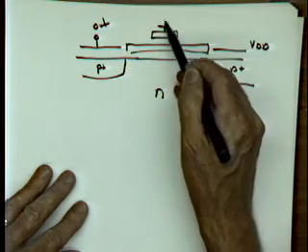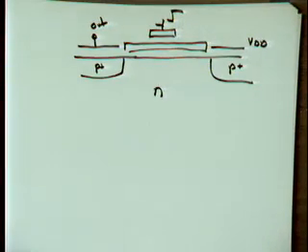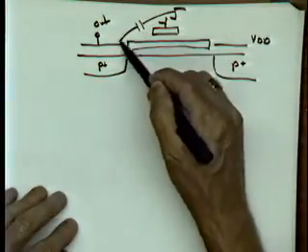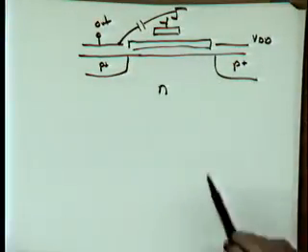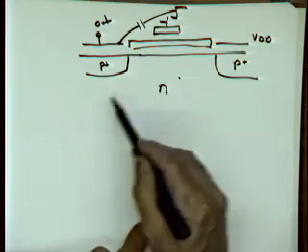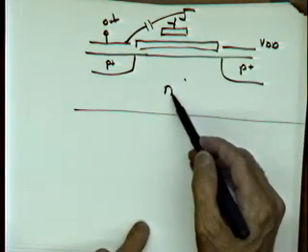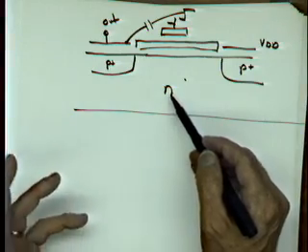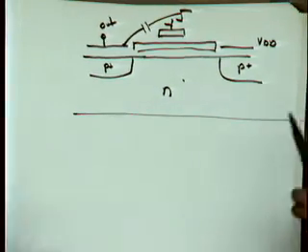Okay, so this gate is taking this big step, right? And now you have this capacitive coupling between here and here. This shoots upwards. Remember the well, in this case, this N material is going to be at what voltage? It's an N well, sorry. It's going to be at VDD, right?